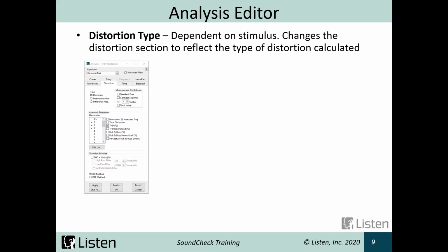If I have THD percentage enabled, I'm also going to output THD to the memory list. So I'll get a total harmonic distortion, and that's going to use the 3 harmonics I have selected in that dropdown. So if I run this step, I'll get an output of harmonics 1, 2, and 3, so the fundamental, harmonics 2 and 3, as well as total harmonic distortion using harmonics 1, 2, and 3 in the calculation.